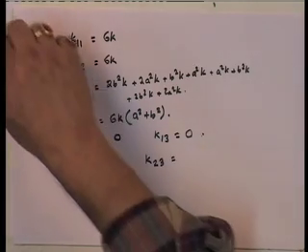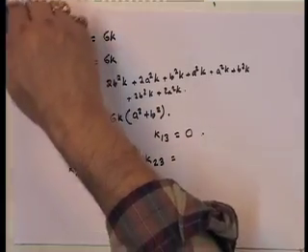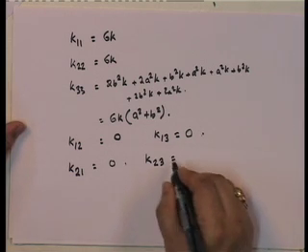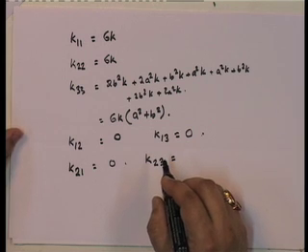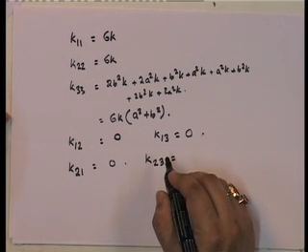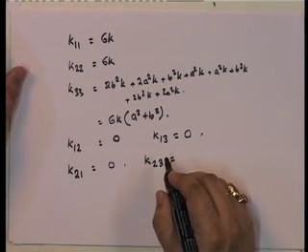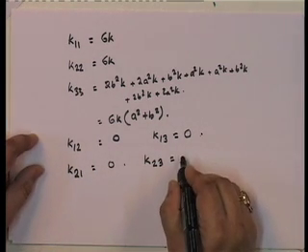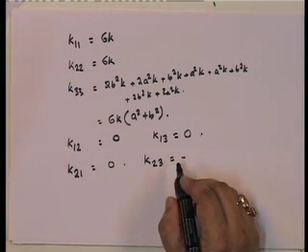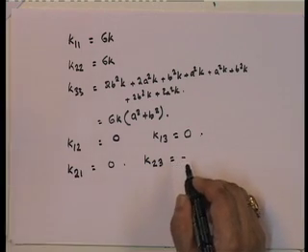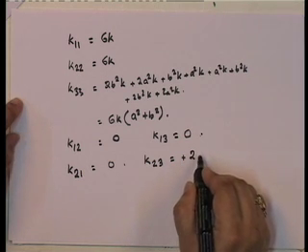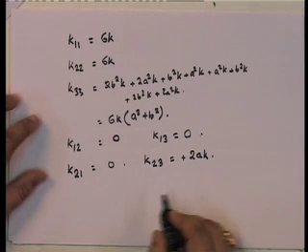So, that means these are the forces which are being subjected to displacement in this direction. So, the work done will be, this thing is in this direction. Okay. So, the work done will be 2k plus 2k, 4ak minus 2ak. So, it is going to be minus, it is 4ak minus 2ak, because this is doing positive work, this is doing negative work. So, in k it becomes negative. So, this becomes plus 2ak.